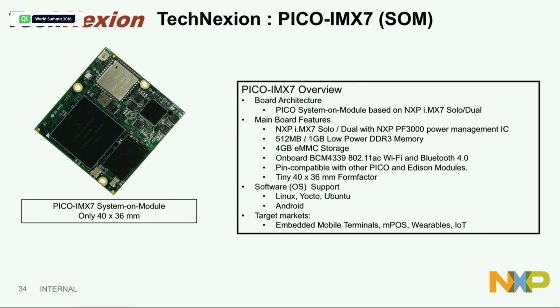Obviously, Toradex, they're based both here in the US and Europe. We have partners such as Technexion that are based in Taiwan. They have their own manufacturing capabilities. So again, they came out with a very small module based on the i.MX7. Again, you don't have to worry about DDR layout, flash, what Wi-Fi Bluetooth module, how you're going to connect it. That SOM is already fully designed. You don't have to touch it. You can go back and buy from them in volume. They're also a contract manufacturer, so they can actually get you to market working with one company the whole way.